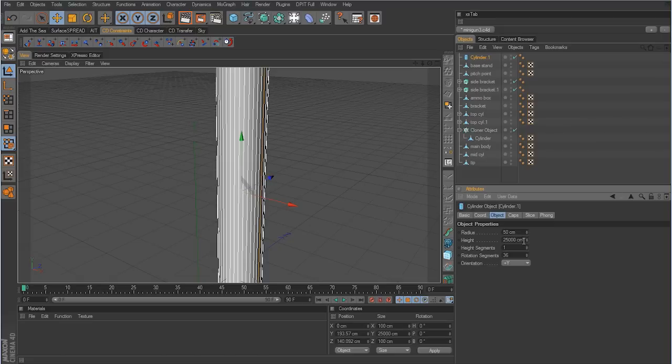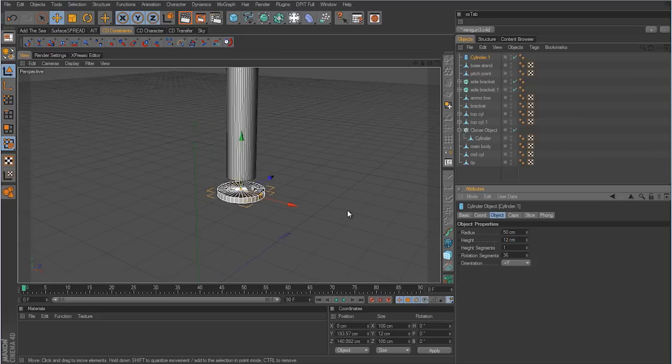So just be sure that when you delete these values out of these attributes here, that you select the CM as well, or just don't even select it, just select the numbers there, and that will keep it from actually going way beyond where you want it. Sometimes I catch myself not selecting everything there, and you end up with a very large value. And another way to get around it is just to double click the attribute, and it will select everything for you. Okay, so I'm just going to give this some more subdivisions, the rotational segments here.